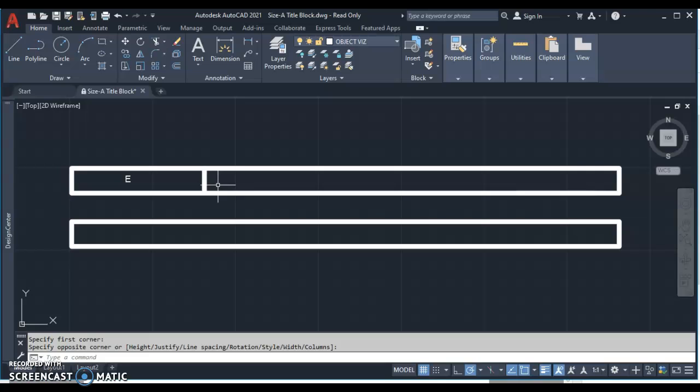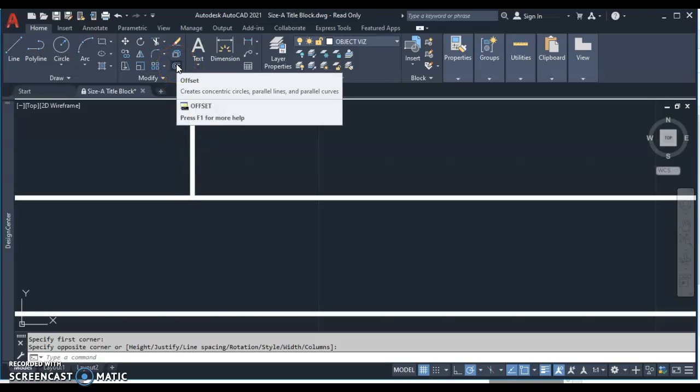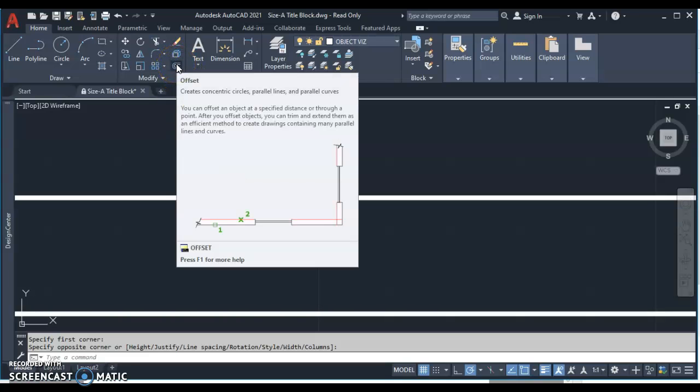Before I start with my next part, I need to factor in the saw kerf. The saw kerf is the material that is wasted by the saw thickness, the thickness of the saw blade. Okay, and my thickest saw blade removes 1/8 of an inch material. So we're going to create a kind of a waste zone here by accounting for that. And I like to use this special tool up here called offset to account for the saw kerf.